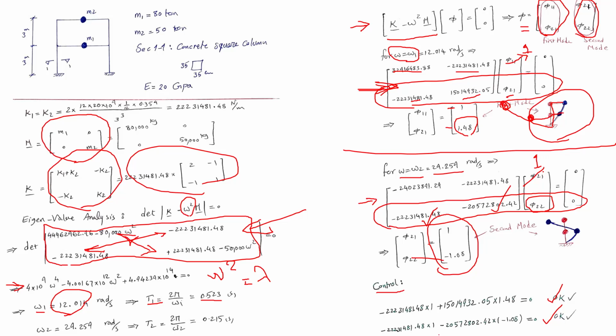They are the inherent characteristics of the structure rather than expressing the effect of external loads. So when you have external forces, the final deformations or internal forces are calculated by combining the mode shapes with other factors which usually come from external forces.